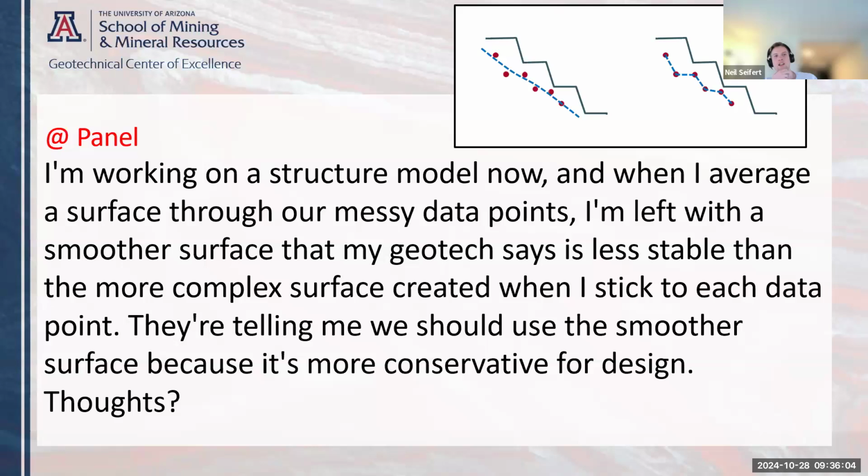And the second part would be looking at the confidence of each of your data points. I would also question GPS accuracy, if your data points are staggered like that. Is there anything else you can figure out around the data points? Are they all the same high quality data sets? Otherwise, I would probably snap your fault mesh to the highest confidence data points first, see if that creates a very smooth surface. If that's still staggered, then I would be looking at a few other things. Very good points. Thank you, Neil.